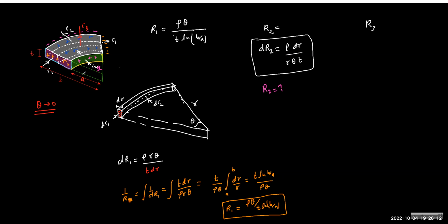You have to think in that way, based on what your terminals are. Rho L by A is a generic formula for uniform cross section, but L represents the length in which current is flowing. So why are you not able to understand what L is in the context of the elementary?